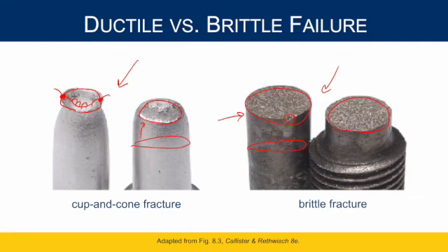So why do you think it failed at that point? Well, one reason would be the void takes up no cross-sectional area, so it's actually taking away from our cross-sectional area at that point. Our cross-sectional area is a little bit smaller, and therefore the force being transmitted through there, the stress becomes just a little bit higher at that point. So that's really why it picks this place right here to fail, because the void changes the cross-sectional area.